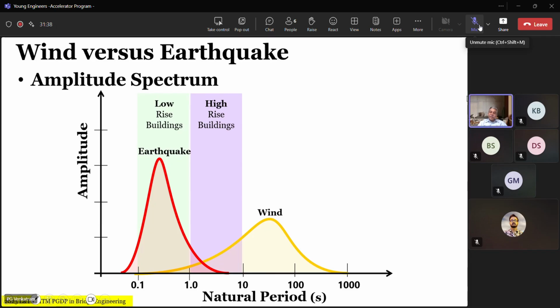Lower estimation of deformation. So when you take the outer dimension, you are underestimating deformation, but you are conservative with respect to evaluation of the earthquake forces. But if you take the minimum sizes, what are you doing? You are overestimating the deformation. You are possibly overestimating the wind effect and the wind dynamic effect.